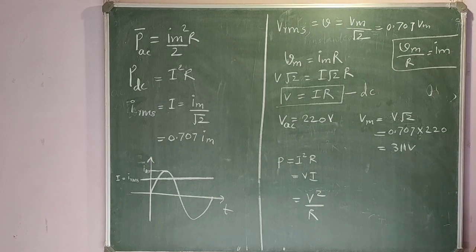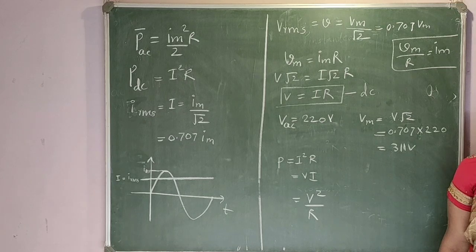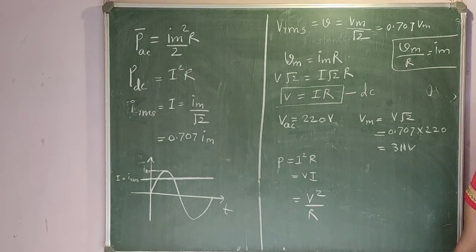So thus we have discussed today the AC voltage source. When it is connected to a resistor, the AC current and the voltage are both in the same phase, and the value of current which we obtain is I maximum sin omega t. The current and voltage reach maximum and minimum values at the same time. So they are both in the same phase, and the average power we obtain is I square R.